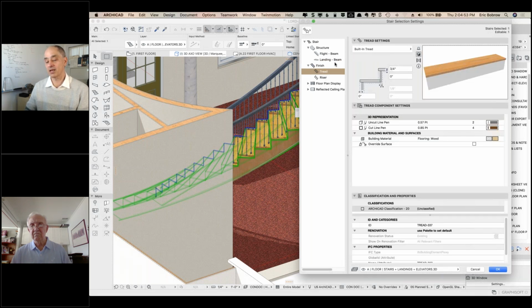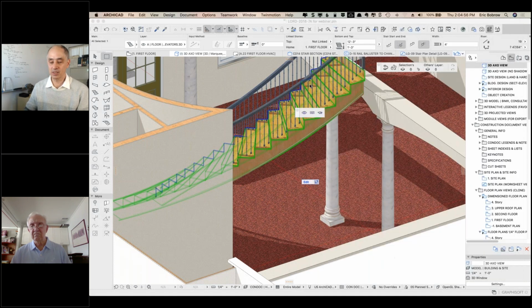So you're basically putting all of that in, and then the blue line that we see bumping along here on the plan is just going to be an arc, simply taking what would be a straight line and curving it, just like curving any edge. It allows you to make it an arbitrary radius or a very specific measured radius. There is a circular setting in the stair dialog where you just put in the specifics of the radius that you want, in and out, or the run on the inner side of the treads.